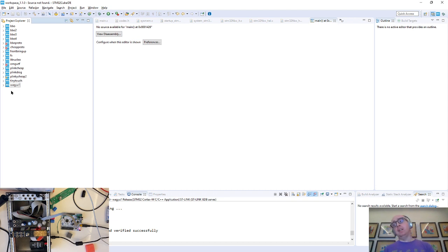Once you're into the meat of software development, you want to do it in an emulator on PC with a familiar environment, or you want to use something like Visual Studio Code, which I haven't taken the time to figure out. But this thing generates makefiles, so it's actually very easy to get Visual Studio Code to build your makefile for you. And they have a really good integrated debugger there as well. I believe there's an ARM Cortex-M4 debugger plugin for Visual Studio Code. So if I had to do this for a day job, that's what I'd be pursuing. But because I don't, I basically bring up the boards in this thing, program in an emulator, and then drop the DSP code back into here.